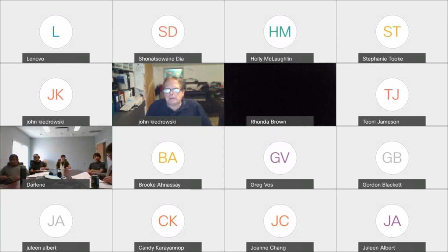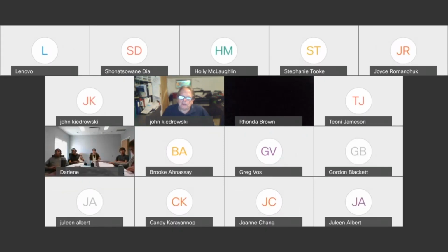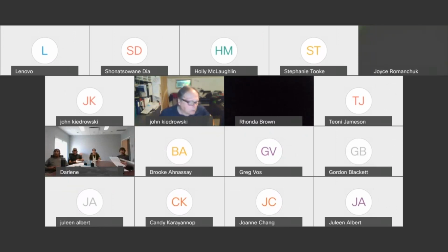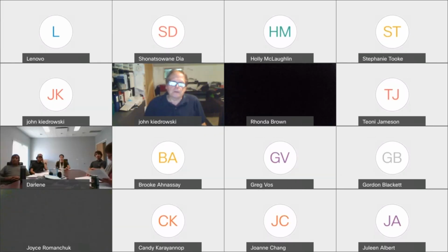The house as a system takes the approach that when we make a change to one thing, there are effects elsewhere. One example was windows: taking the old windows out and replacing them with more energy efficient windows. They will save energy, but we might find the building conditions change internally, and the new windows may start to cause condensation that the old windows didn't exhibit.